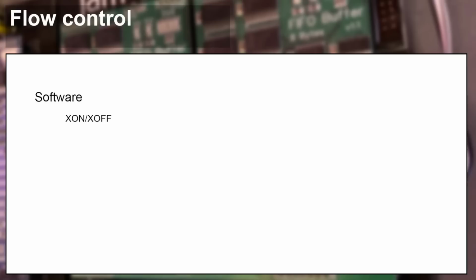And the other type of flow control is hardware. Now, I most commonly see the variant that is referred to as RTS/CTS. There are other types, but most importantly, on modern USB UART connections of the type I'm using to connect the CPU to my PC to transfer data to and fro, RTS/CTS is the one that's supported by all of those that I've seen. So that's the one that I want to focus on here.